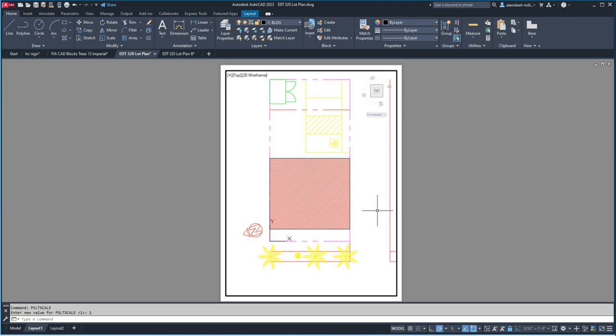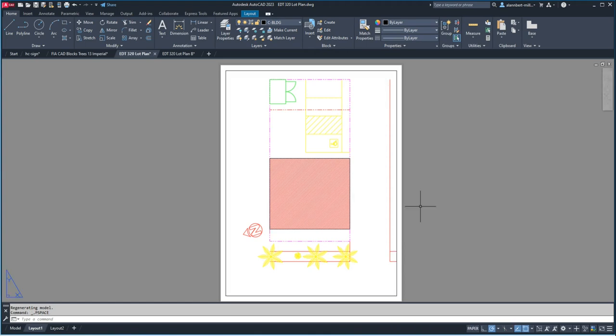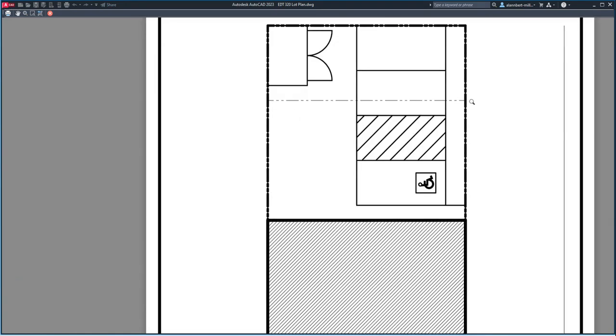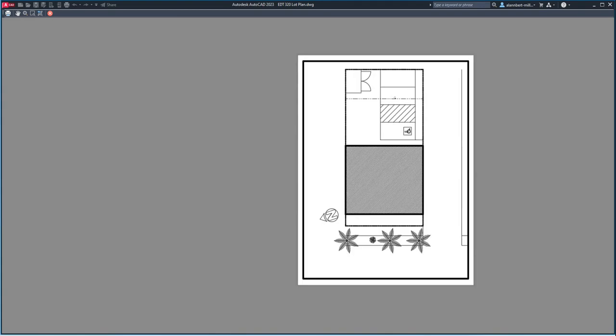So for people like me, I set the paper space LT scale to off, and then it won't affect until you regen. And then I want to be in charge of the LT scale inside the drawing, and I want it 24, and I wanted to print it like that. So if I go outside now, double click, and then type in preview, okay, I should see now the line spacing. I mean, the dash spacing. Some people call it dashiness, so I can see that clearly.